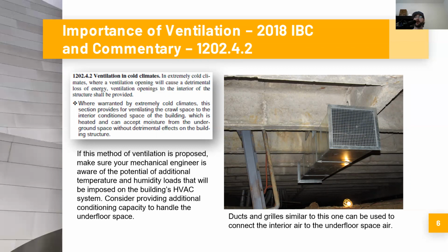You're simply allowing the area of the crawl space to vent into the interior. And so there are some additional considerations as far as humidity and temperature loads that would be prudent to consider, or have your mechanical engineer consider, just in case this necessitates additional conditioning capacity to handle the underfloor space.